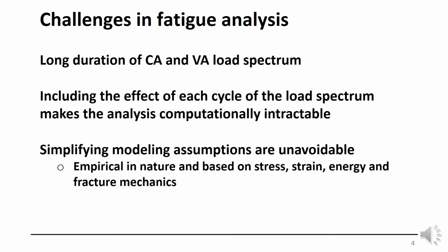So the challenge in fatigue life analysis is that, because of the long duration of the constant amplitude and variable amplitude load spectrums we have, including the effect of each cycle of the load spectrum is computationally intractable. So therefore we end up with some simplifying modeling assumptions. They're either empirical in nature or based on stress, strain energy, strain, and related to fracture mechanics type concepts.